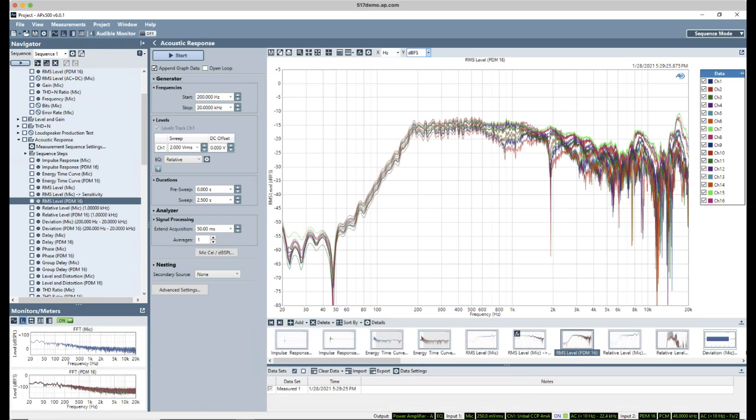So from a test perspective, you make one frequency response measurement, then you occlude the port and make a second frequency response measurement, and then very often you'll express the result as the ratio of the two, with a pass-fail limit that describes the attenuation with the port occluded. Essentially, if something busts through that limit line, you'll have a failure of the seal somewhere in your device.